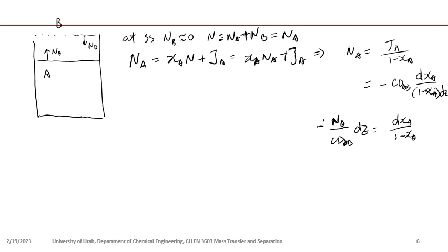So here, what you need to understand and remember is, first, the assumptions to get Fick's second law; secondly, when you apply Fick's second law, you need one initial and two boundary conditions; and thirdly, given a particular situation, you need to be able to translate the problem statement into proper boundary conditions. For the ground contamination problem, you should be able to translate that the boundary condition is constant concentration here and constant concentration 0 at infinity, right?